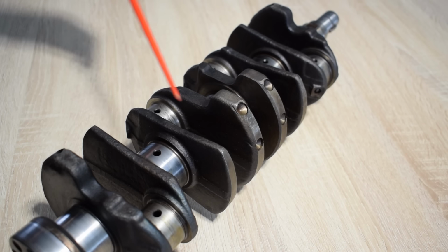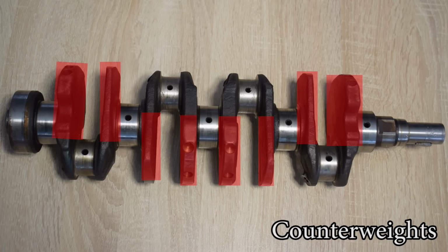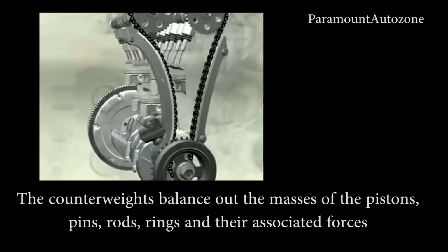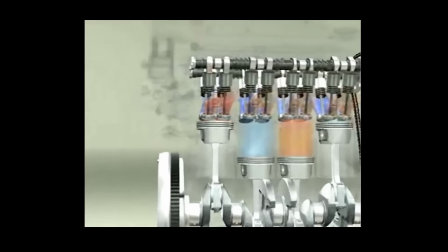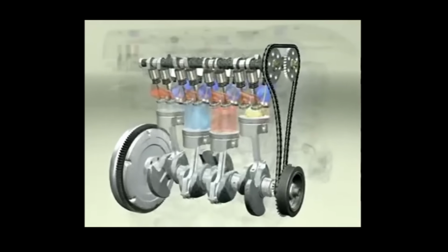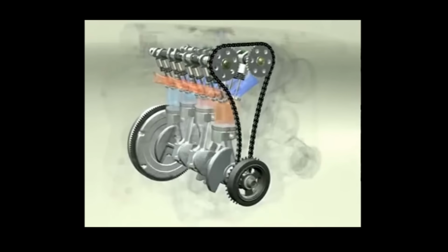These big chunks of metal are the counterweights. Now, the operation of an internal combustion engine generates strong rotational forces, and the mass of the piston pin, the rings and the connecting rod moving up and down at high speeds generates a very significant force that is exerted onto the crankshaft. The counterweights have the task of balancing out these masses and forces. We will talk more about counterweights later in the video.